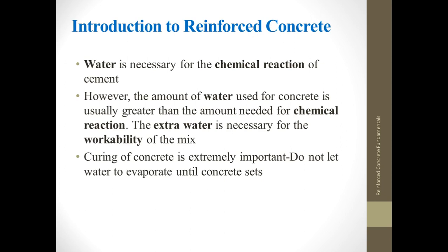As we mentioned, we are also adding water to the concrete mix. Water is necessary for the chemical reaction of cement. Without any chemical reaction, we would not have any concrete. But the important part is that the amount of water used for concrete is usually greater than the amount needed for a chemical reaction. So, what is this extra water needed for? Well, this extra water is necessary for the workability of the mix.